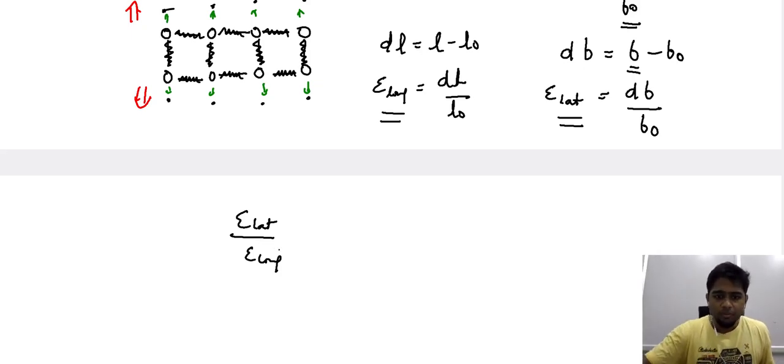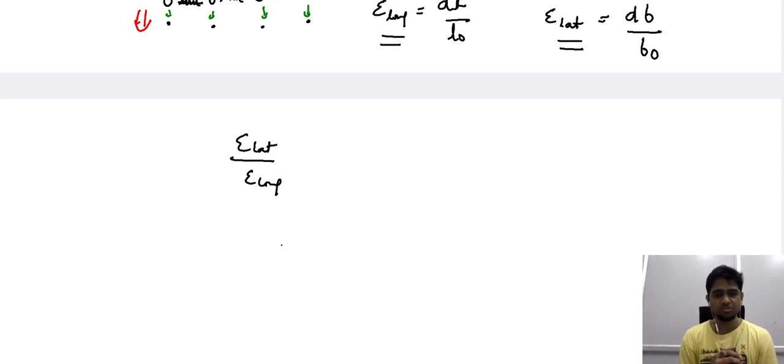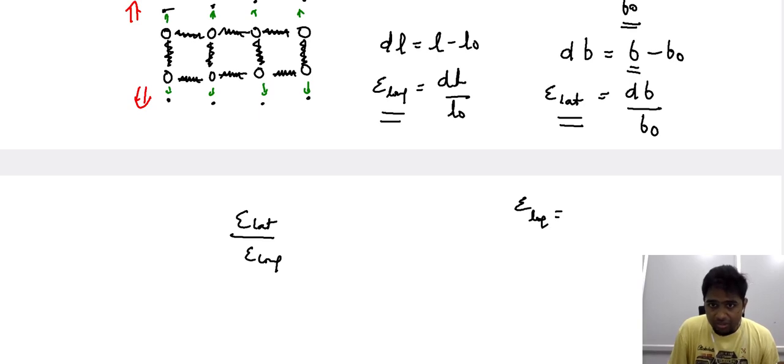Now, before we give a name to this ratio, let us consider one critical aspect of these different forms of strain. If you reconsider the terms associated with the longitudinal strain, it is the elongation relative to the original length. So it is L, the length of the sample under the imposed loading condition, minus the original length, and the ratio is taken with respect to the original length.